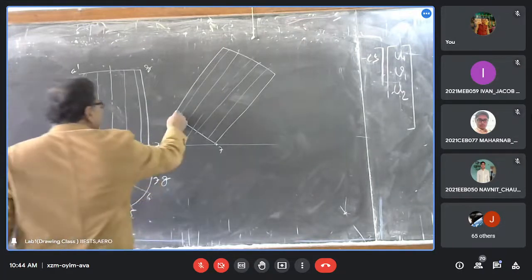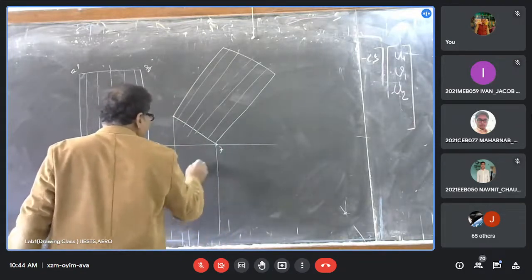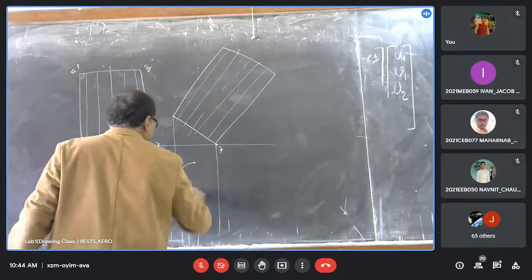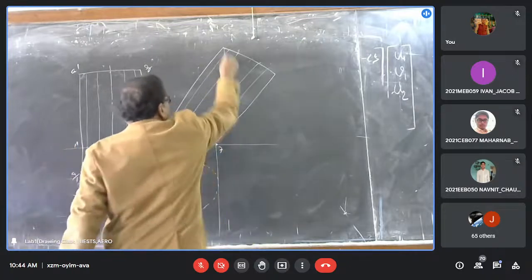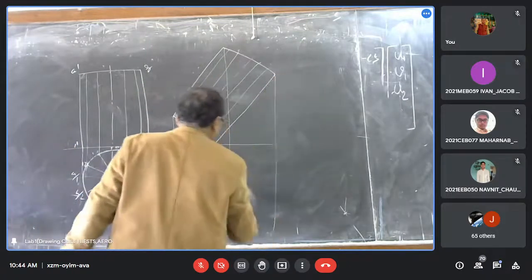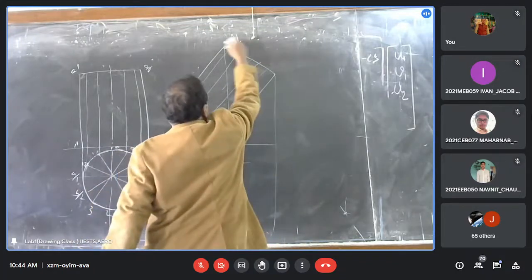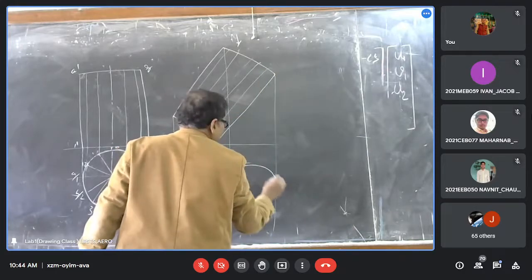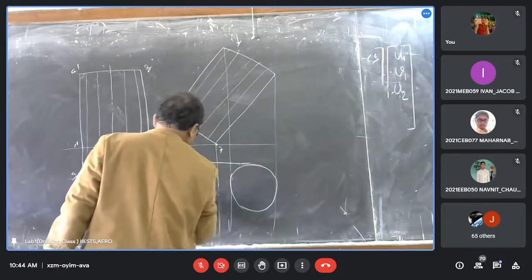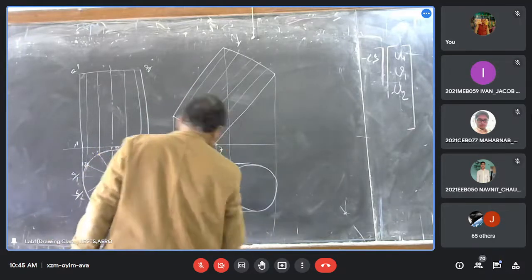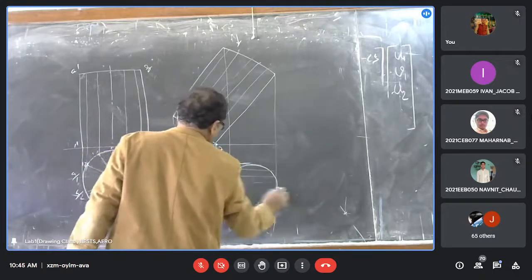Then draw a projection. In between these two lines, you can see an ellipse, but you cannot see the half portion. This is dotted. But in the top view, you can see the total ellipse, because while you see the top, you can see the total space. Okay, then draw a tangent line. Also draw the generating lines, all the generating lines, as thin lines. Okay.